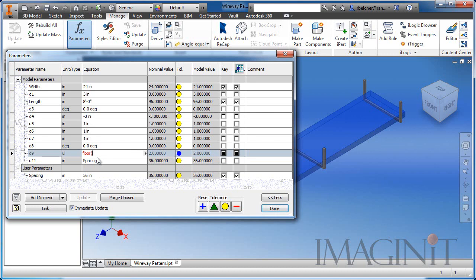Now, I want to use the length value up here. In order to use that, I'm going to have to isolate it. Isolate is a function that allows you to convert units. So I'm going to isolate, in parentheses, the parameter length. I'm going to put a semicolon here, and I'm going to type in the default unit. Then we'll do a semicolon and do the desired unit. So we want to convert length from inches to UL, and we'll put that out.